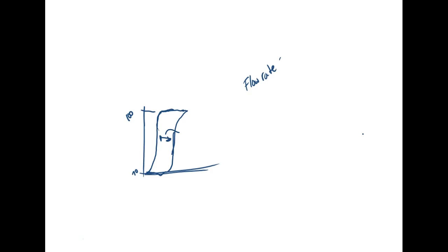Another thing that happens is you get pulsation. If you ever did spray painting, and you run out of tank and it starts running on your compressor, then your spray painter is going to pulse. You're not going to do it really good. A lot of people that do really good spray painting use what they call continuous run compressors, where they use turbines and stuff like that, and they get exactly the same flow rate all the time.